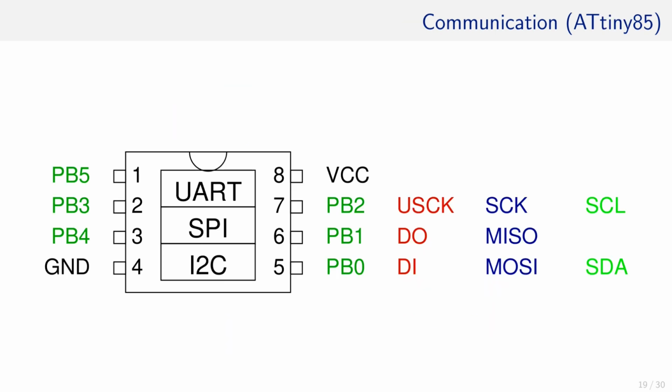That is not possible in the ATtiny. Here, the modules cannot work in parallel, and either the UART or the SPI or the I2C interface can be active since they share the same pins. That means at least two of those modules are just sitting there consuming power.